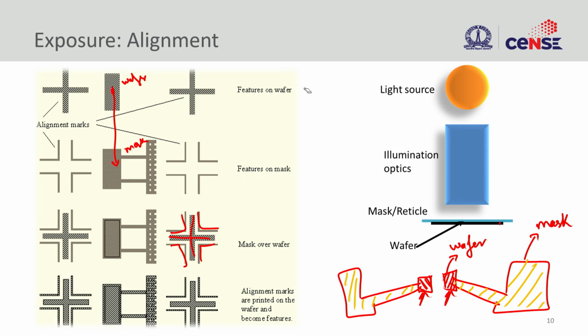So, in order to understand how to put these alignment markers, let us look at the alignment marker placement. If I take a circuit, and then I have some circuitry, let us say something like this, in the middle, I always put the alignment markers at the corner. If you want to be very careful about this, we can also put more number of alignment markers.